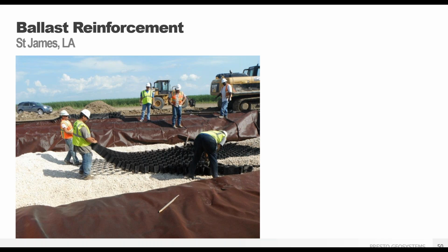And what we like to do, especially where we have a base underneath the GEOB, or in any kind of rail project or road project where you have a subgrade or a sub-base, is make sure that you wrap that geotextile around the sides so you don't lose any of that material. Once you start compacting and you get cyclical loads, it's going to squeeze that material right out. So you want to make sure you basically burrito wrap the sides.